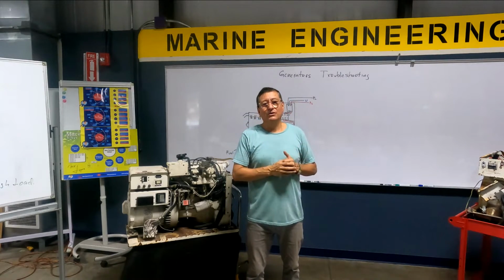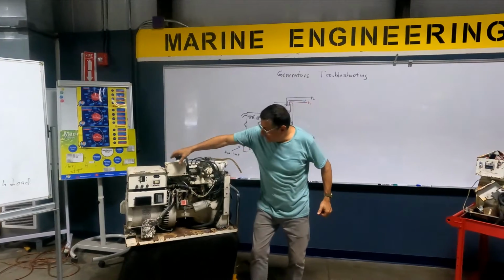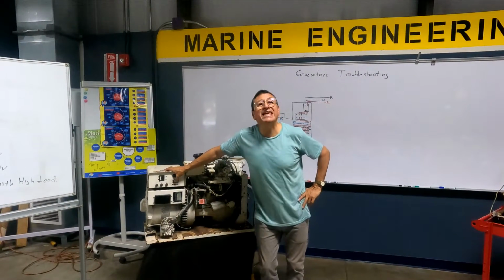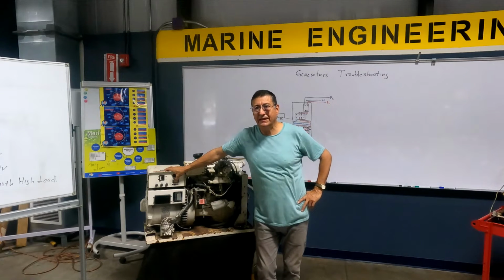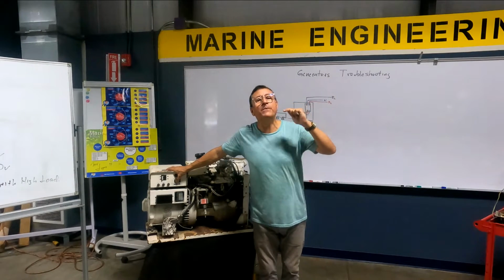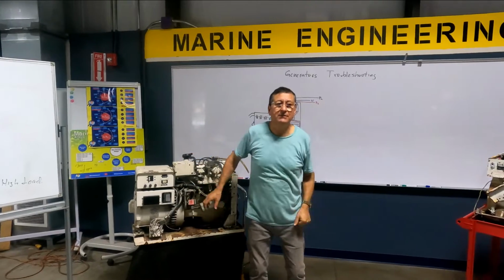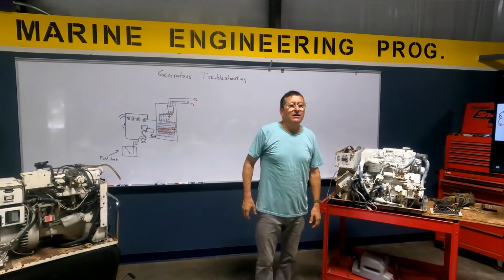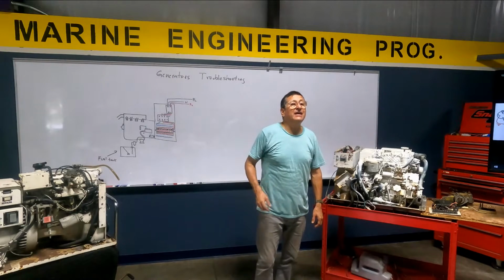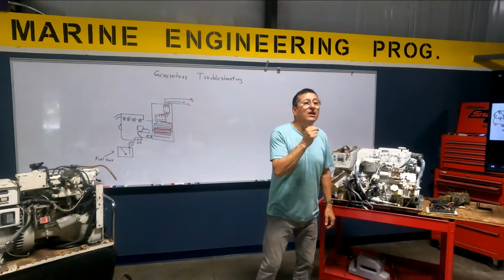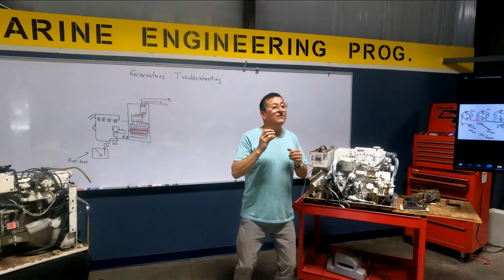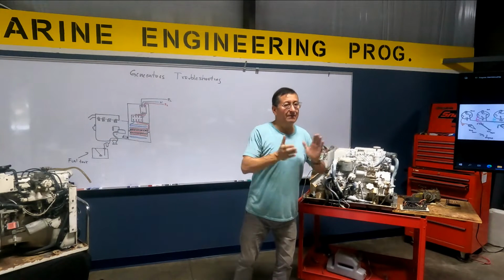Mechanical issues. You remember, my friends, that you have one button, start, other stop, and preheat. You remember preheat? You remember what is the function of preheat in diesel generators? It is to preheat the combustion chamber with the glow plugs, so once the fuel enters, it ignites easily.